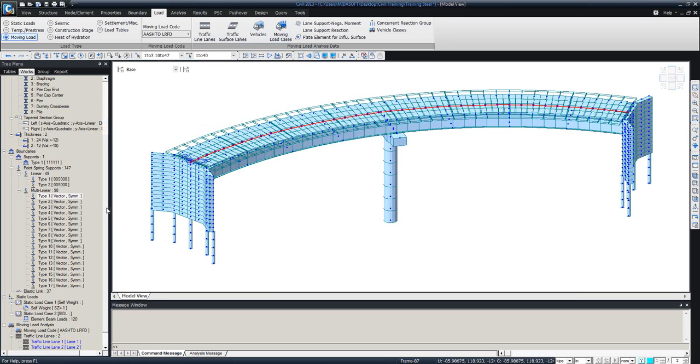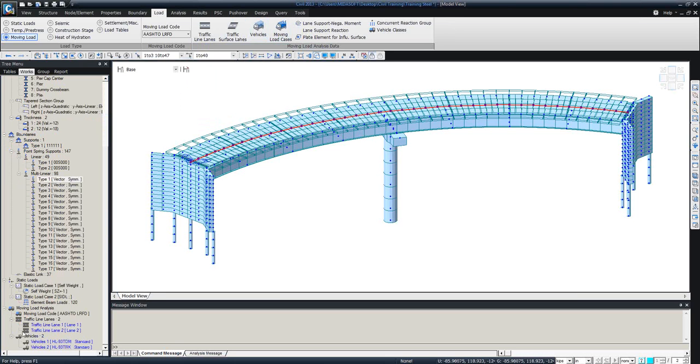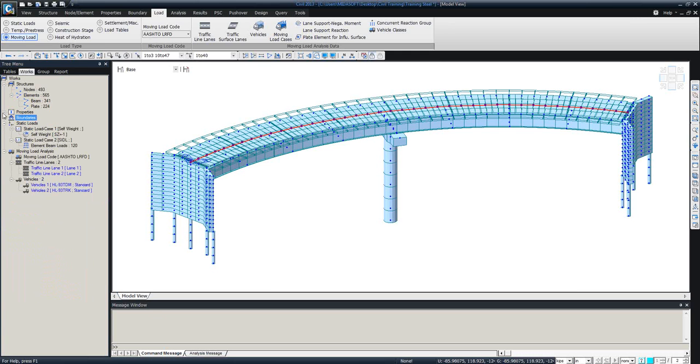And now let's set up the moving load cases. So far you see all the lanes and the vehicles that are defined showing in the blue. When any option here shows in the blue, it means that it's not assigned to anything yet. It could happen to the elements, to the properties, to the sections, and also the material as well. All right. How to apply that?